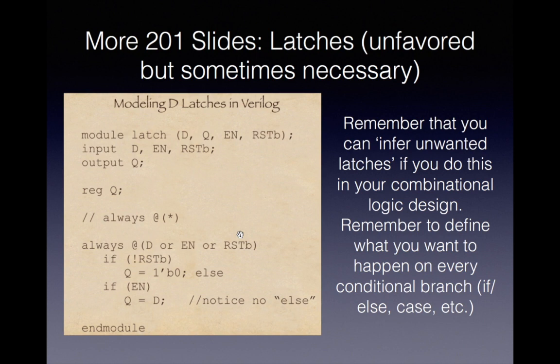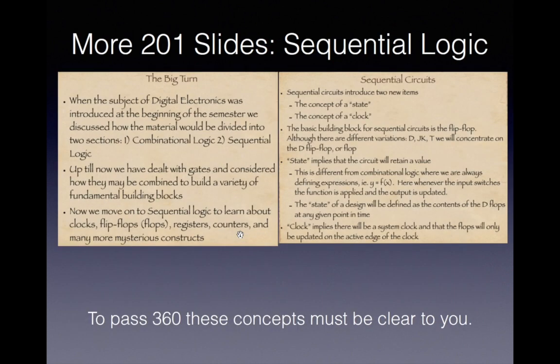So understand what a latch is, know how a latch operates, know that there are times in the digital world where a latch is useful, but ensure by your style of writing your Verilog that you don't infer unwanted latches.